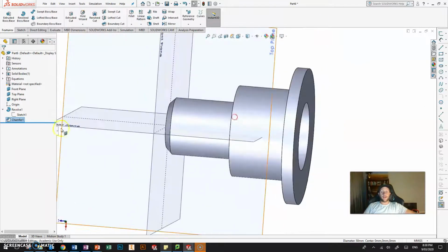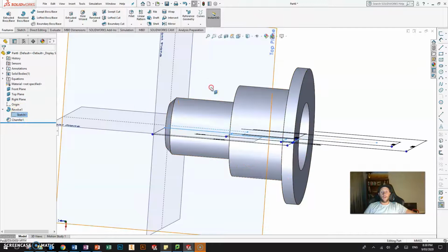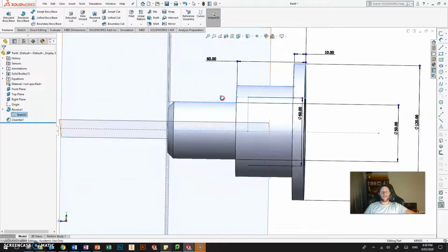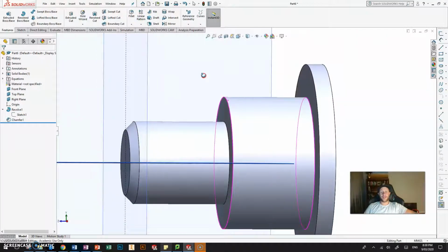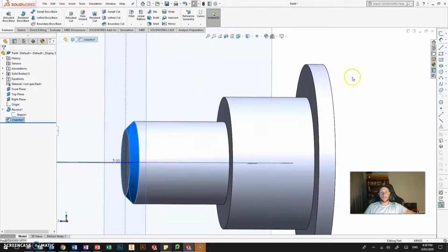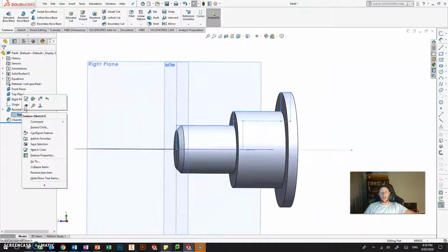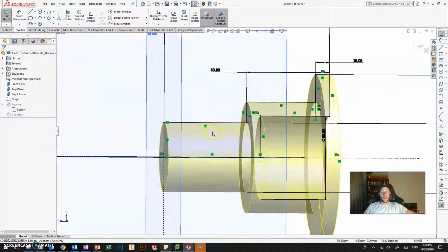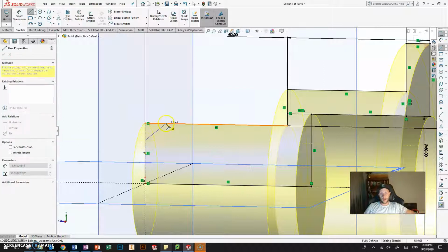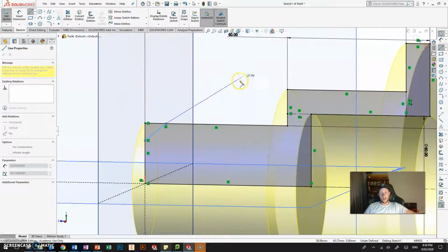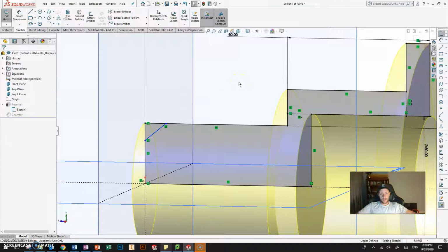Good practice when you're doing a revolve, if you wanted to do a design that has those chamfered edges, I suggest doing the chamfers or the fillets as a secondary feature on the end here, because you'll find that trying to do it in the sketch adds more complexity. So I can do that. I'll show you how that works. If I draw a line across here, just right click on escape.